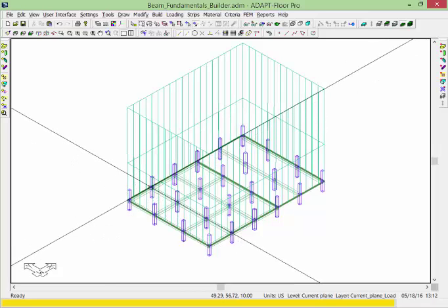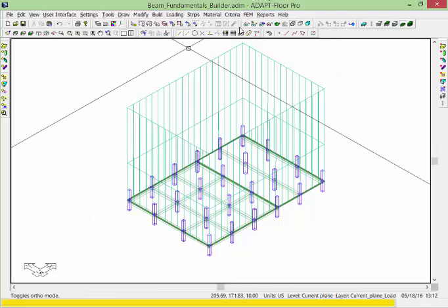In order to design the beams, we need to now set up what we call support lines. The support lines dictate to the program how the design should be carried out, whether it should be carried out using two-way slab criteria, beam criteria, or one-way slab criteria. And this model has essentially all 3 inside the model. So we have the need for first setting up our support lines.